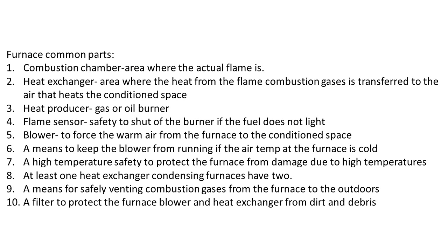All furnaces have a combustion chamber, a heat producer, a flame sensor, at least one heat exchanger, a blower, a filter, a means of protecting the heat exchanger from too high of a temperature, a way to ensure that cold air is not blown into the conditioned space, and a method to dispose of the combustion gases.